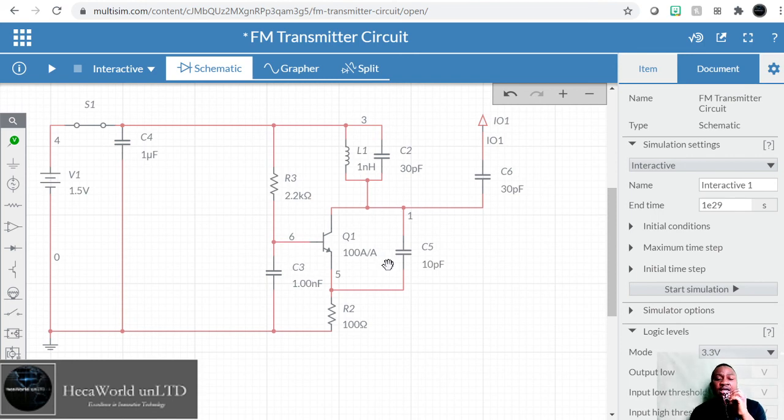So do this, let me know what you find out. Replace this one nF capacitor with a 27 megahertz crystal, and remove this circuit here. Just put any inductor here. You don't need this 30 picofarad or variable capacitor here. Just put any inductor here to complete the circuit. Replace this with the 27 megahertz crystal oscillator.